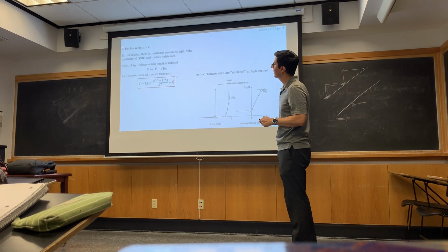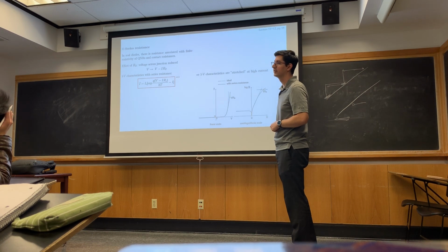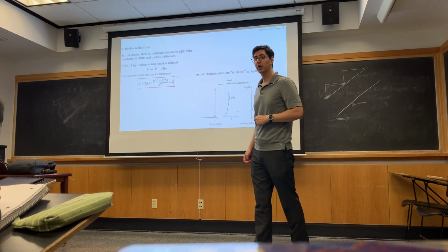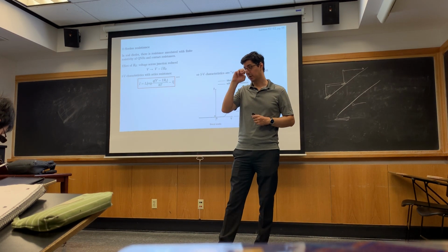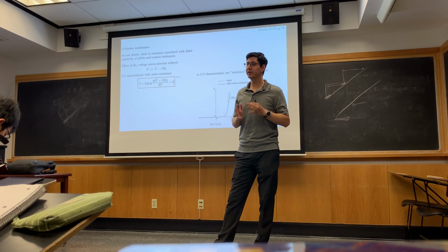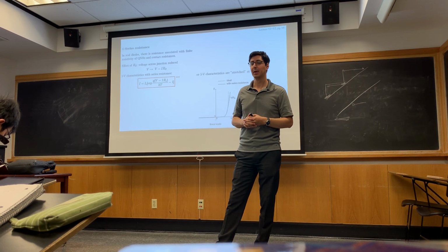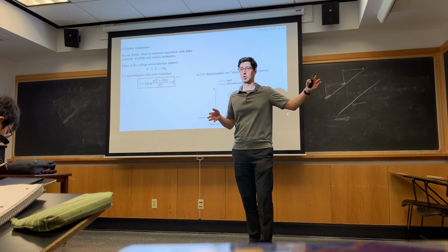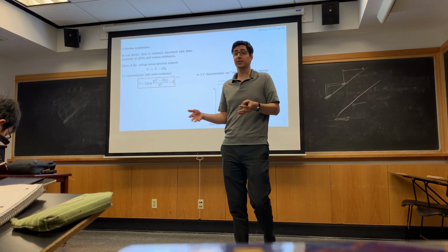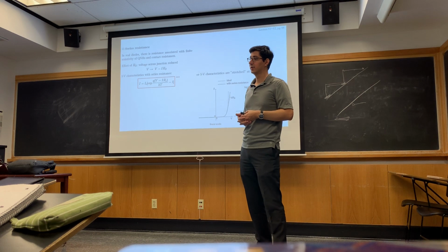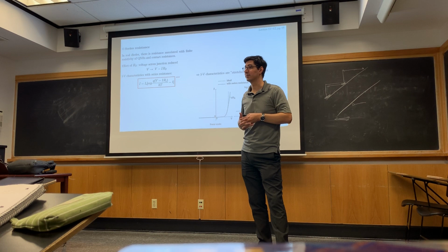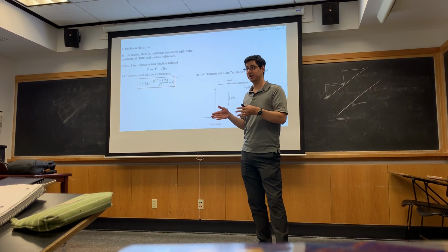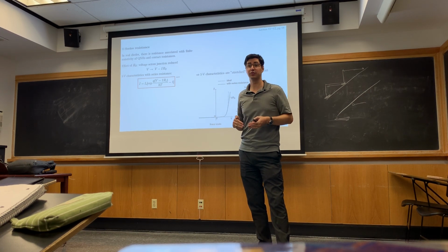Another thing with diodes, another non-ideality, is series resistance. So far we have assumed that if we apply some voltage across the diode, all of it appears across the junction. Well, let's assume I have very long quasi-neutral regions. They have some finite resistance to them. And so for them to carry some current, some voltage has to be dropped across them. They're not infinitely conductive. Now, you have to think about it as series resistors.